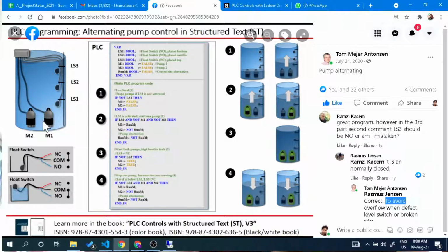So alternate the two pumps in different scenarios instead of running one pump continuously, because that can heat up the pump body and reduce the lifespan of the pump. So better is to install both pumps and run them alternately, half this time, another half next time. This program is done to do that only.